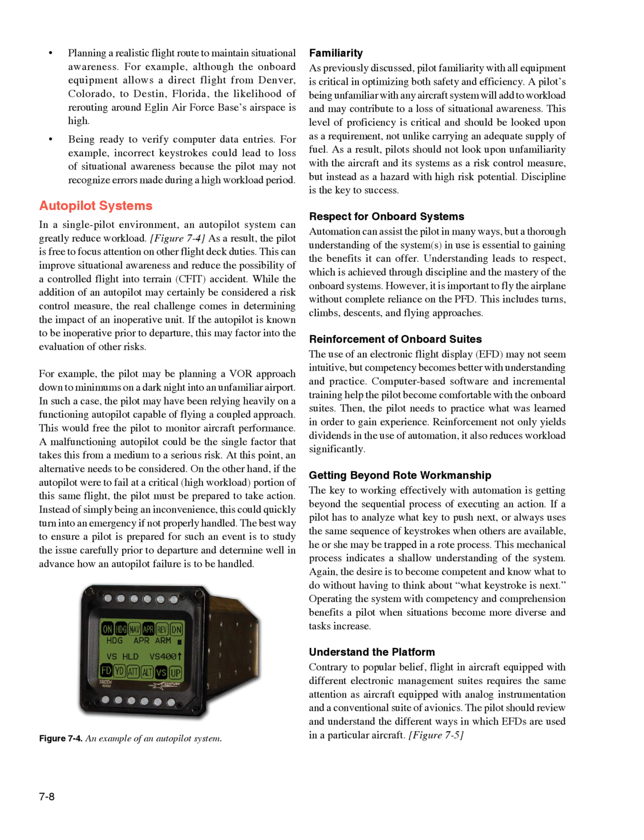Being ready to verify computer data entries. For example, incorrect keystrokes could lead to loss of situational awareness because the pilot may not recognize errors made during a high workload period. Autopilot systems in a single pilot environment. An autopilot system can greatly reduce workload. Figure 7.4. As a result, the pilot is free to focus attention on other flight deck duties. This can improve situational awareness and reduce the possibility of a controlled flight into terrain, CFIT, accident.